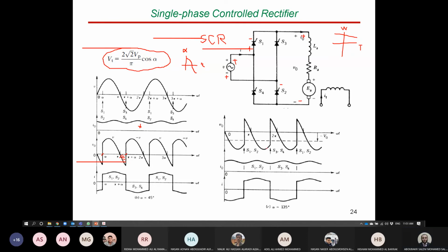Okay guys. As you can see here in this part, the voltage became negative, and the average voltage became negative here, and the current is in the same direction, which means now the power is reversed. This is at alpha equals 135, and this curve here is at alpha equals 45. So this is representing motor operation at that quadrant in positive, and the other direction here representing the operation at that quadrant. This is not reverse motor, however; it's called regenerative braking for the reverse motor.